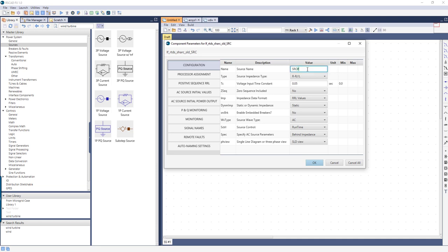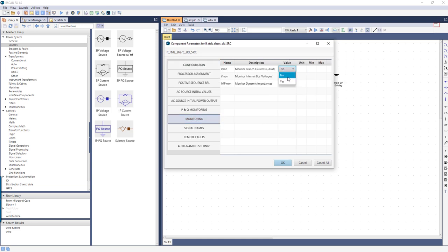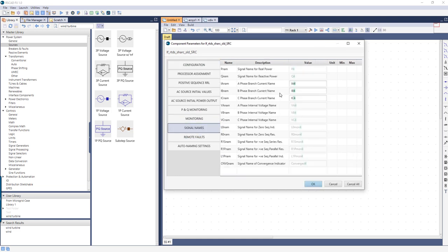But when I click into that field to edit it, I can see that the enumerator is represented by a number sign. And that number sign is a reserved character. It's used only for auto-naming. So anytime you see that number sign, it is representing the enumerator. It's included by default at the end of most character fields, most text fields in the parameters, but the user can move it around.